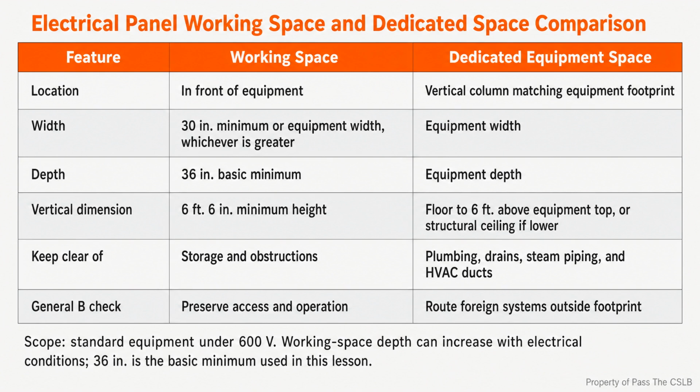Breaker location has its own measurable limit. The center of the grip of the operating handle, with the handle in its highest position, must not be more than 6 feet 7 inches above the floor or working platform. The measurement is to the center of the grip, not to the top of the panel cabinet.